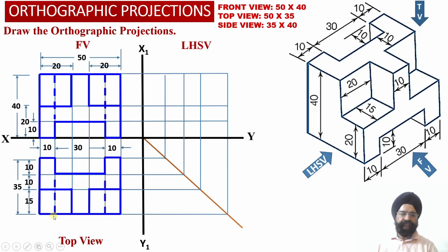So here we can check two vertical edges corresponding to this wall and this bottom wall over here corresponding to this rectangular slot will be observed in the form of hidden lines into the top view projections over here. So this completes the construction of the top view orthographic projections of the solid.